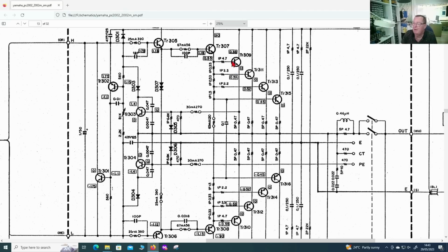So this here has about 0.55 of a volt on. That's just switched on. So as soon as we start getting any audio waveform, the transistor turns more on. The reason they do this is you call it base bias, and that's because you want the transistor to start conduction as soon as the audio waveform goes above 0.